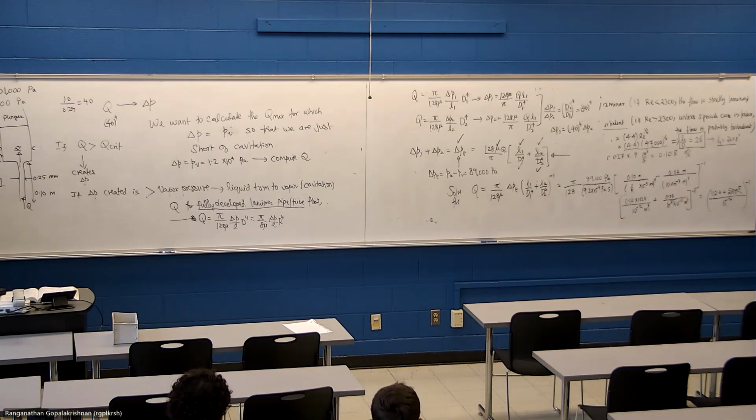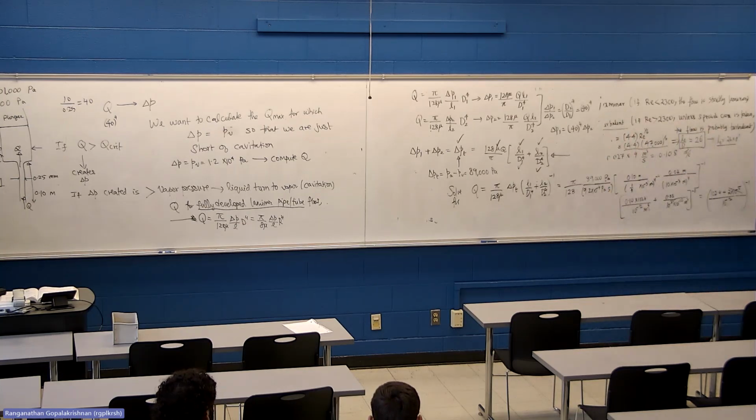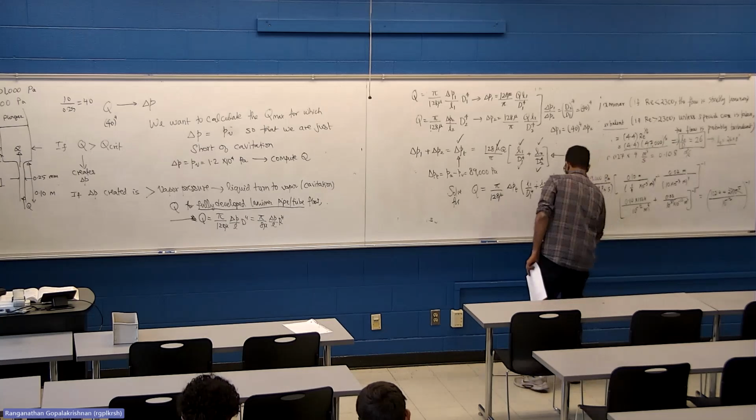Are you going to say something? We didn't actually define delta P1 and delta P2. No, I did that because I wanted to make this point. If I just asked you not to worry about the syringe, you wouldn't know why. Now you know why you don't need to worry about the syringe. Almost all the pressure drop is in the needle and almost none of it is in the syringe.